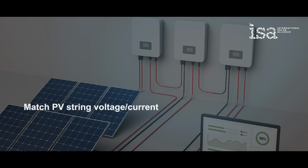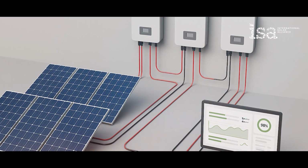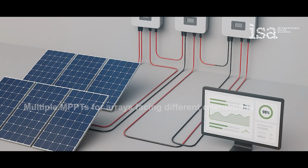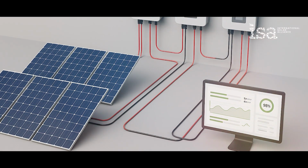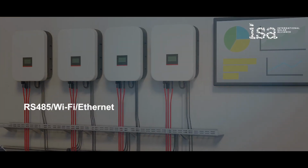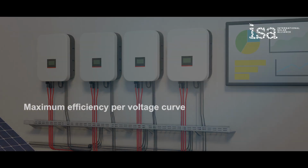Match PV string voltage and current with inverter input ratings. Use multiple MPPTs for arrays facing different orientations for maximizing the efficiency of the whole system. Integrate monitoring via RS485, Wi-Fi, or Ethernet. Optimize string length for maximum efficiency per voltage curve.